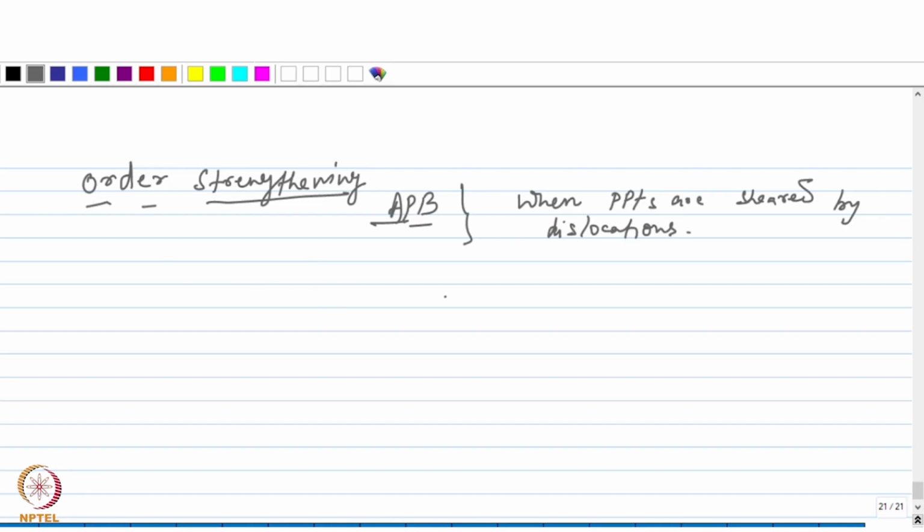this kind of non-deformable precipitates will actually stop the dislocations till the stress is raised and the dislocations break free, right? But in this case, as the dislocations encounter the precipitates and as you keep deforming the material or as the stress is raised, that dislocations can actually shear through the precipitates, right? So these are shearable precipitates. So once that happens,